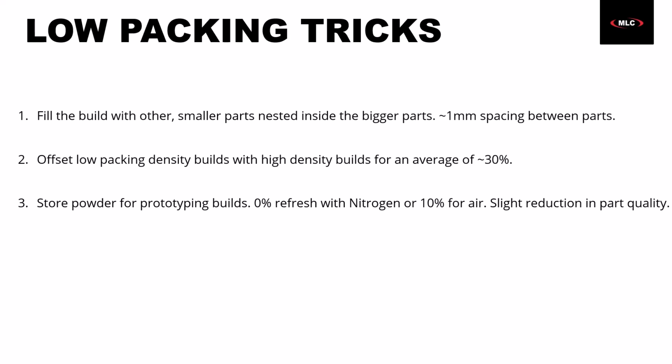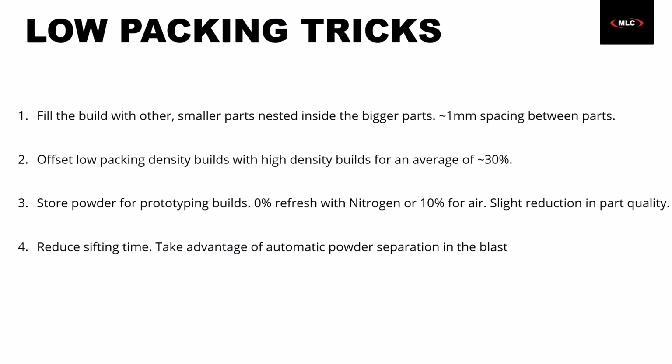And then there is one last option, and this one's pretty convenient. It's that you don't have to spend as much time in the SIFT. So where you might normally spend 10 minutes sifting and trying to get all the media off, or all the powder off so you can reclaim it, now you only need a few minutes in the SIFT, and then you can let the blast do the rest of the work, which works out perfectly because the blast has an automatic powder separation. So that keeps your blasting media from degrading by being totally saturated with printing powder. And then later on, you can just dispose of that excess powder. And again, you can sort of absorb that into your cost per part.